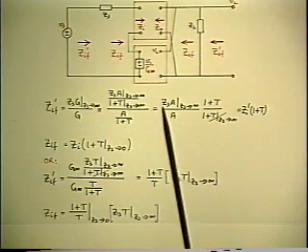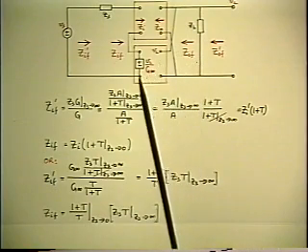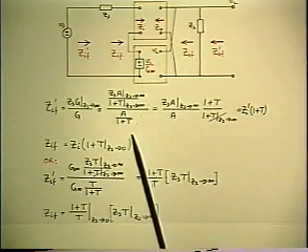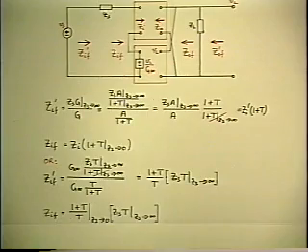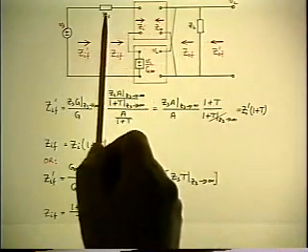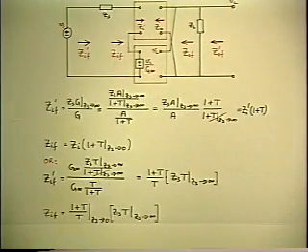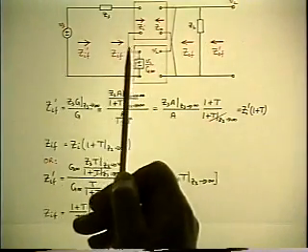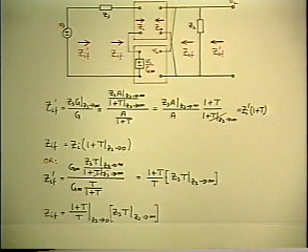Which is consistent with the expectation that this connection of feedback raises the effective input impedance in order to make the overall voltage to voltage gain less sensitive to ZS. And the way it does it is by making the input impedances much bigger than ZS.